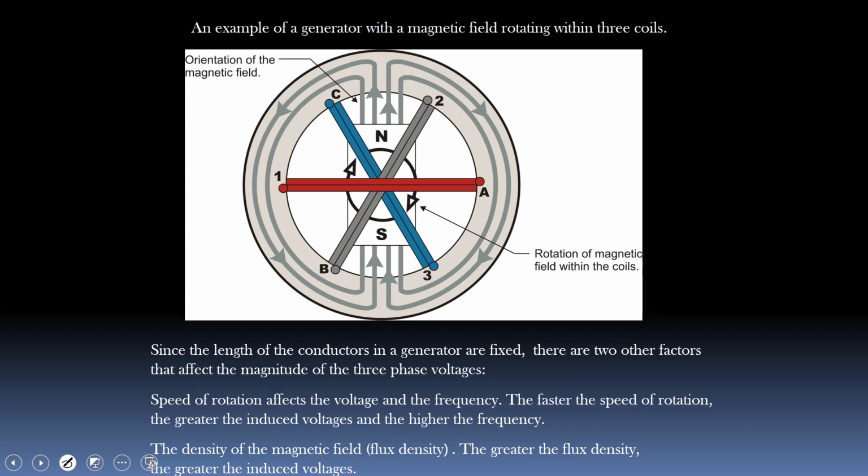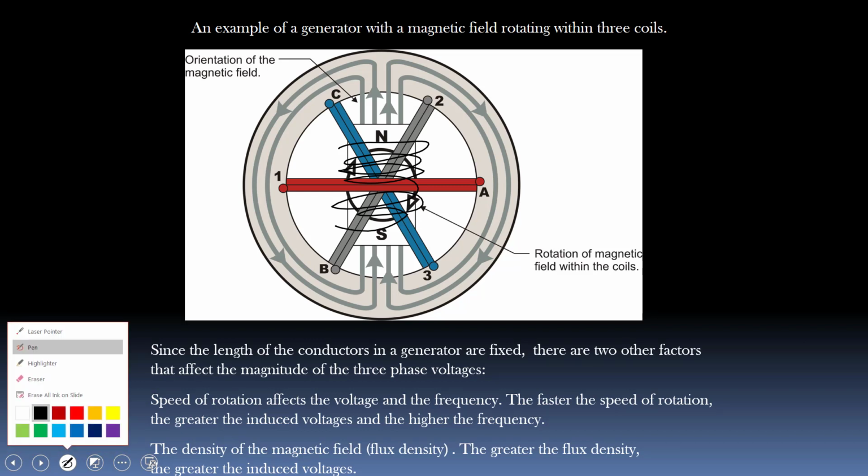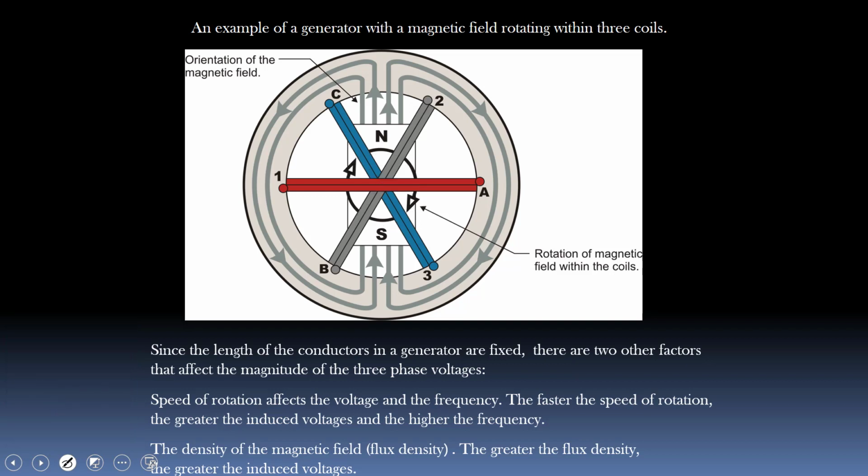Now in this one, we just kind of got a crude picture with a permanent magnet. Okay, in reality, this is a coil, so that we can adjust the voltage to that coil, make more current go through, increase the flux density output on that electromagnet in the middle, or we can decrease it as needed. So if the voltage is too high, we can drop down the voltage across that electromagnet, or the exciting field we would call it, whatever the excitation current is. So we'd adjust the current through the electromagnet, and then we could adjust the output voltage of our generator. But when we're looking at the stator windings, we're talking about 3-phase, it's still the same concept. Each winding is mechanically 120 degrees apart on this simple generator.